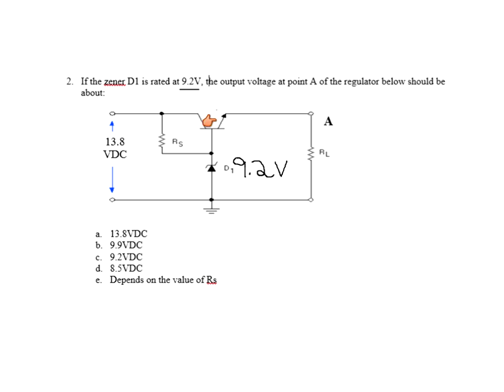Looking over here, I got 9.2. Remember how to solve this? What's the voltage drop of this base to emitter junction? 0.7. So what happens here? I have 0.7 volts right here between the base and the emitter. Now, we got rid of this answer. That's not right. We got rid of this answer. It's not right. There's only 2 answers left. Do I subtract or do I add that voltage? Well, we know from this point right here to this point, the diode will drop 0.7 volts. We talked about that. So I'm going to lose 0.7. What is the only possible answer here, therefore? Right there, how about that?